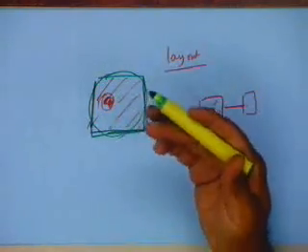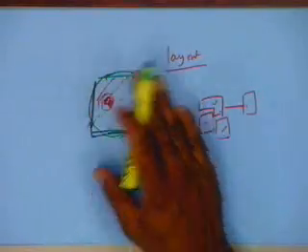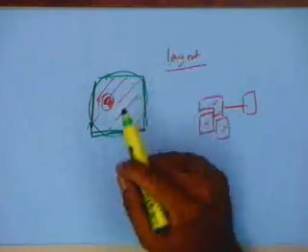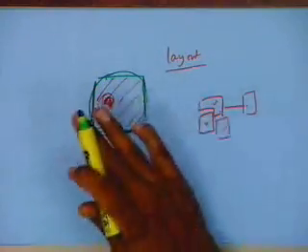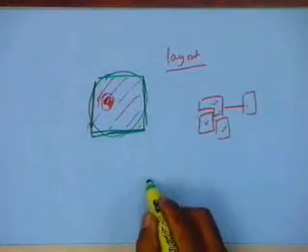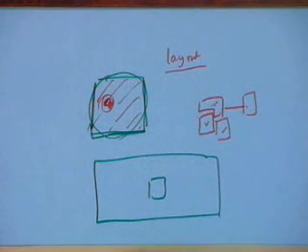In packaging, they talk of material which is thermally conducting but electrically insulating. A lot of work goes on materials like this which can take this power off, because a chip which is 1 centimeter actually gets packaged in a fairly large package, almost 10 times the area or even more.